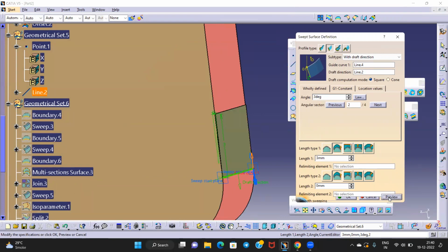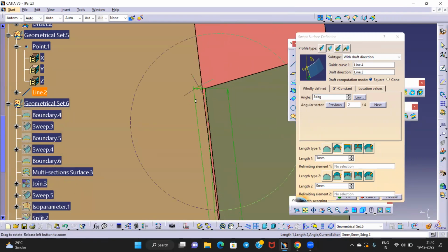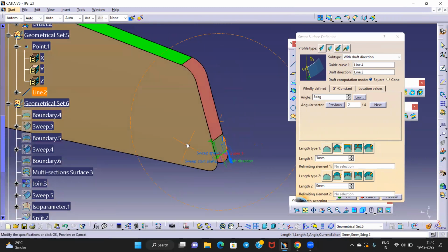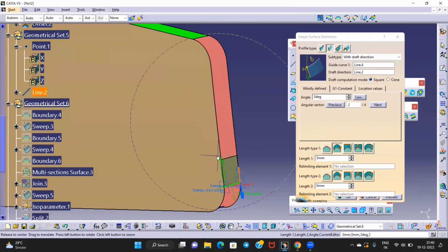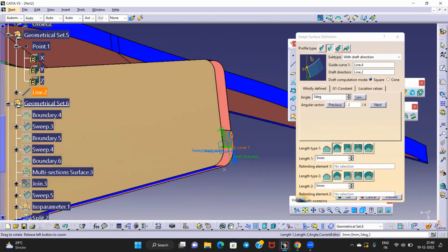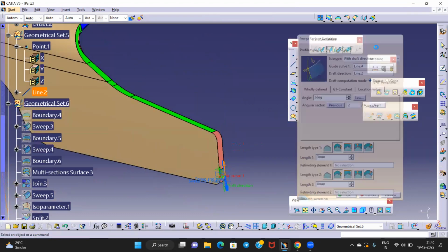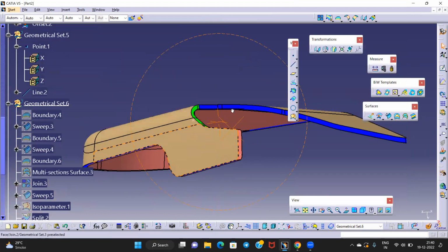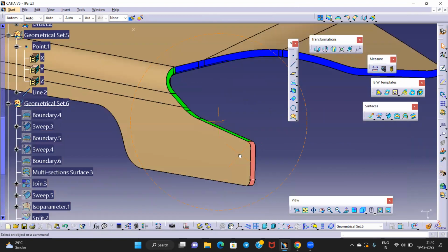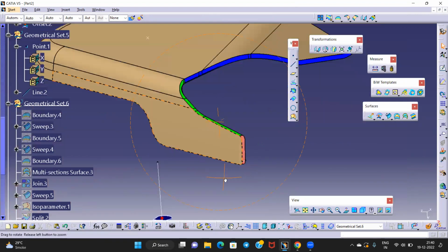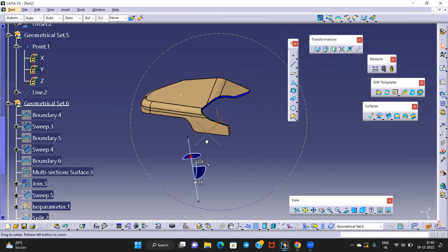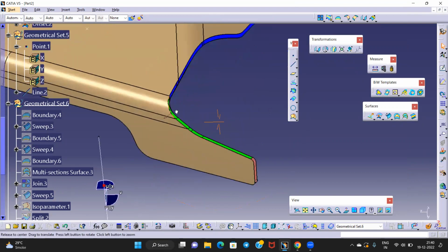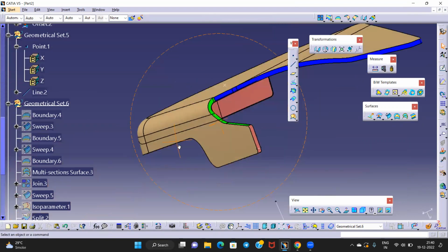If I am putting this, we have to increase the A surface on this side. So A surface we cannot make changes to, right? If they say you can cut some surface, that is fine. This patch I'll show you how to do, but try till here and save this part; in the next session I'll solve this, and the first catches also. But today's topic was drop direction. Always make a perpendicular patch with the drop direction. For C surface, if you are making a perpendicular patch, the drop direction is very important.